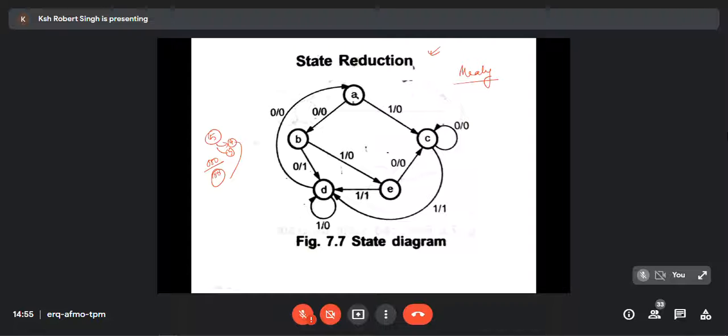So here, let us see whether I can reduce my states or not. I'll give you an example. Now I'm in present state A. Input X, 0 or 1. Like this you write. It will be easy for you to design, instead of writing an X is equal to 0 column, an X is equal to 1 column, and then putting all those things.